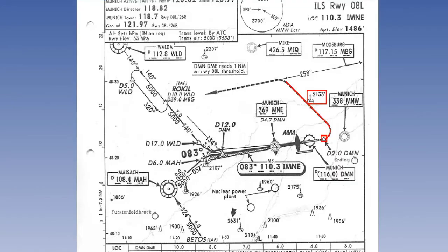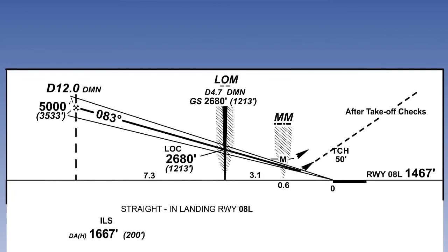If you remember, it took us over a high obstruction, which we won't be able to see if we are in cloud or fog. We must be on QNH to know that we are clear of it. As part of the go-around procedure, we will carry out the after-takeoff checks. These include setting climb power, raising the gear, setting the flaps as required, and several others to get the aircraft into a cruise rather than a landing configuration. They are vital to safe flight.